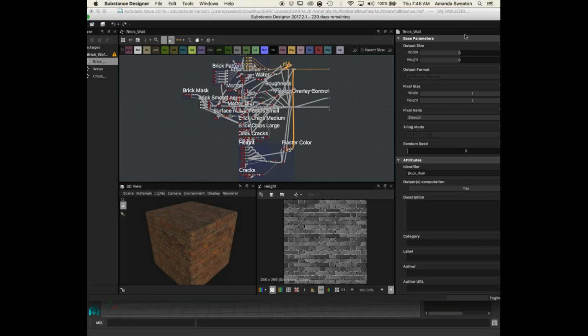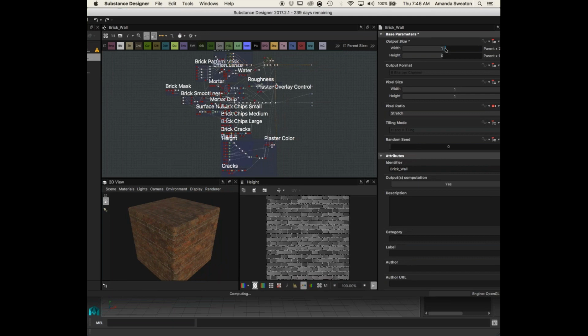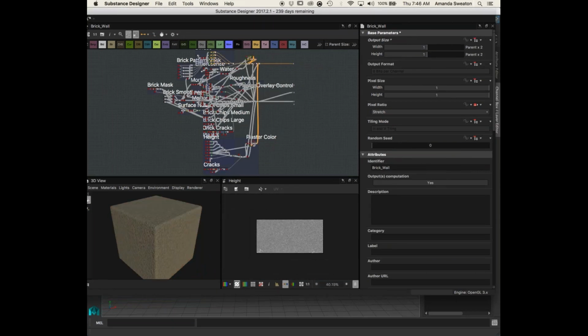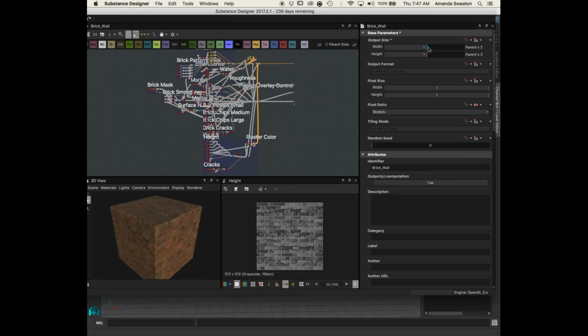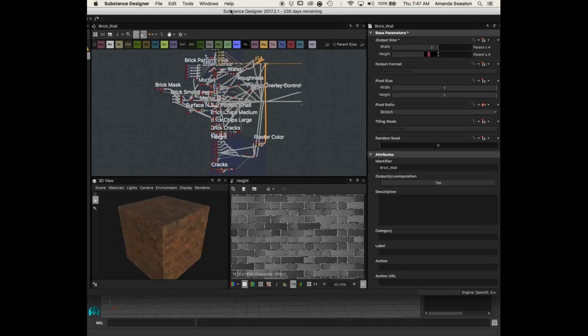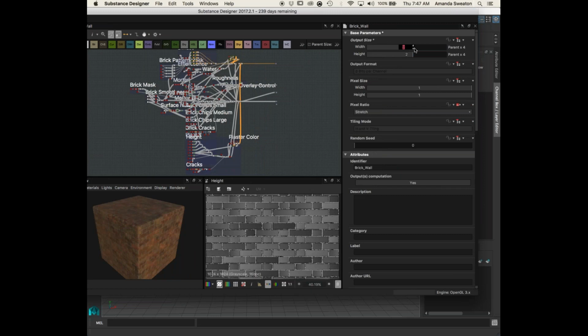So again, if you guys need a refresher, when you download Substance Share materials or Substance Source, by default they will be 256 by 256. So increase that size. If you're working fast, you may forget to check these. And if the resolution does not look good on your materials, I'm going to notice. So I'm just going to do a 1024 for these, so I'm okay with that. Actually, I'm going to do a 2048. My other ones are 2048. I kind of want to match that resolution.